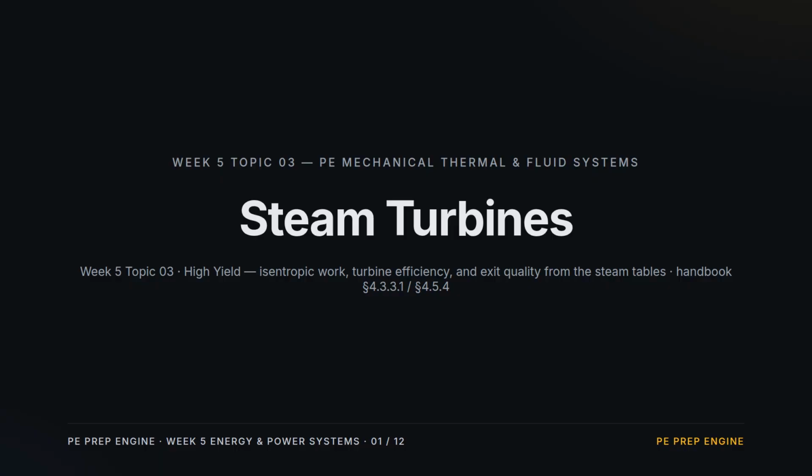Topic 3 of Week 5, Steam Turbines. A turbine turns a drop in enthalpy into shaft work. We set the ideal isentropic limit from the steam tables, then scale it down with isentropic efficiency to find the real work and the real exit state, including the moisture that erodes blades.